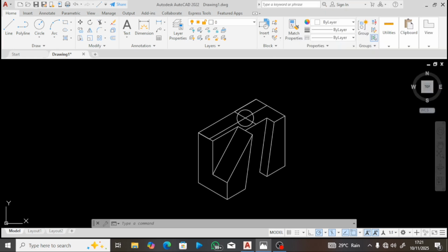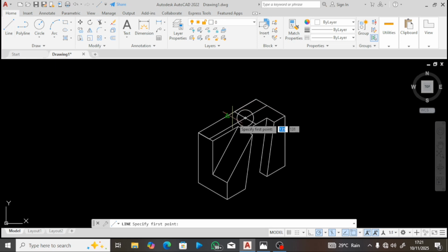How are we going to do it? So I will come here. I will need to draw another circle before I then trim those parts we don't need. So come here, pick a line. This isometric circle here has a diameter of 20, right? So I will need to go down by 20 here, by 20 here to form the box first.